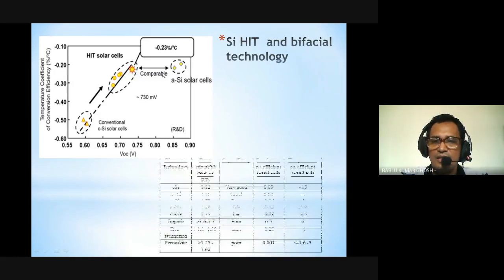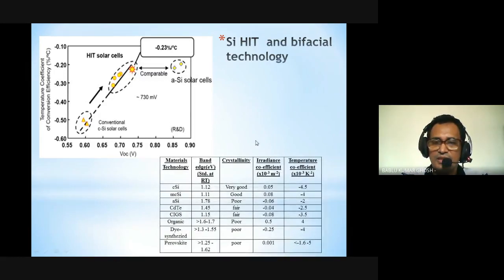photovoltaics. And here you can see the data lines for different materials, showing how they respond to temperature and irradiance, because both temperature and irradiance act concurrently to impact the energy efficiency or performance of solar photovoltaics. In those cases, you can see the different materials have a negative temperature coefficient, meaning it can reduce the voltage and efficiency with the temperature effect.